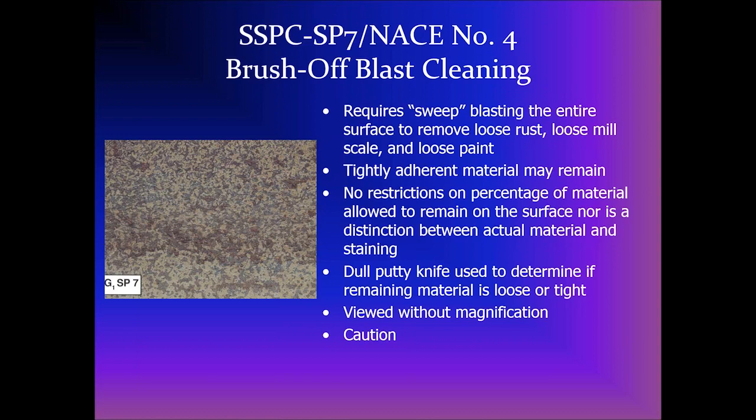Now, magnification does not mean you cannot use a mirror. A mirror is not magnification. It is permitted. It means you can't use a microscope or a magnifying glass to look at the surface. A caution: when using brush-off blast cleaning on existing coating, you need to be careful that the coating is sound enough to withstand the rigors of brush-off blast cleaning. In other words, when you abrasive blast clean, the abrasive may come out of the nozzle 400 miles an hour, so it can really beat up the existing coating.